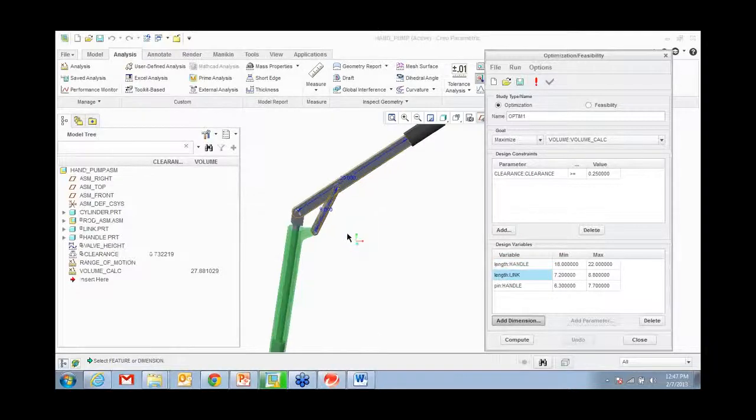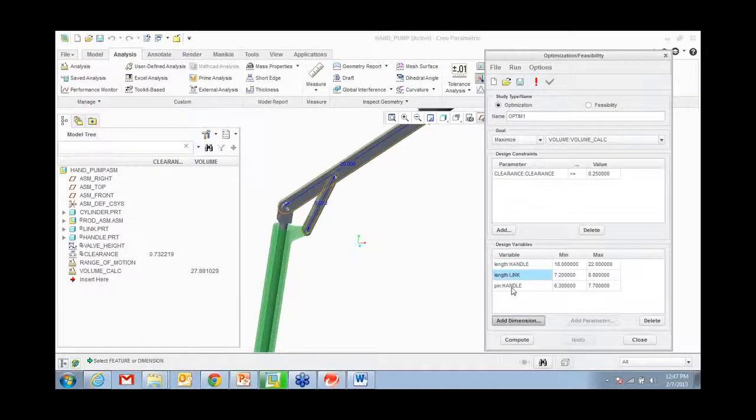Looking for a distance between this hole and that little hole over there. Trying to find out that belongs to the link part. So in the protrusion, that's the link. So let's look at that. There you go. That distance. Sorry about that, guys. It just won't let me pick very easily. So there you are. You have a dimension that's the overall length, you have a dimension which is the length of this link, and you have a dimension for that hole position.